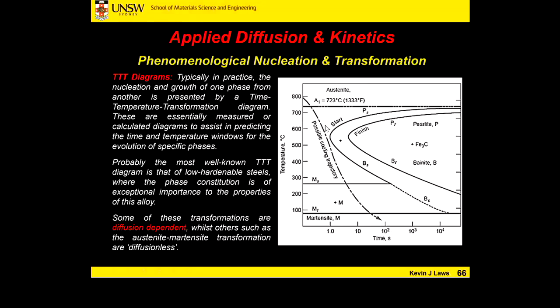We can see within this curve here that at high temperature we're going from this austenite, FCC phase. We're passing through transition into our equilibrium phases, which would be over here. But we're not cutting through these boundaries here.